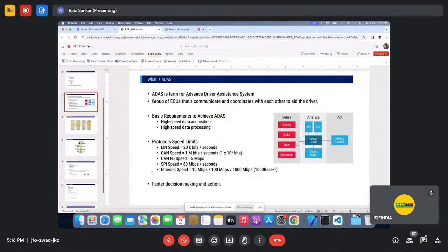Earlier, the ECUs were distributed. They get connected over Ethernet or CAN or whatever, but it's quite distributed. We cannot know which zone is doing what. But now we are adapting to a different kind of computing in the automotive world, which we call domain based architecture. Different zones are identified in the car, let's say front, left, right, rear, and there is a central HPC computing.